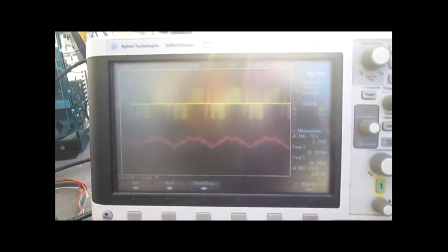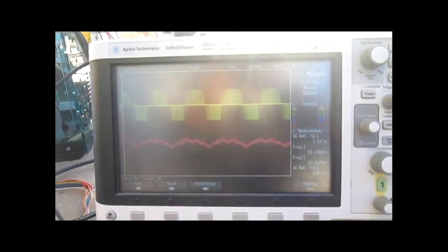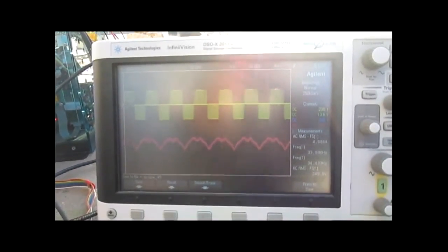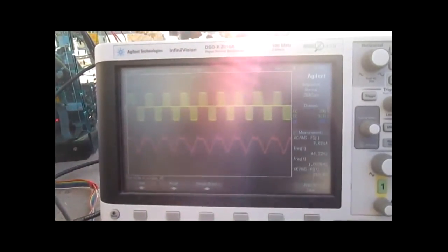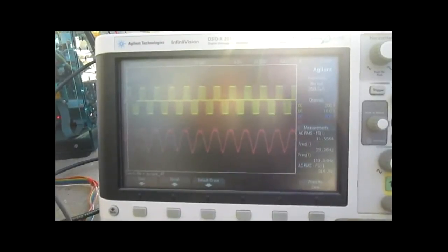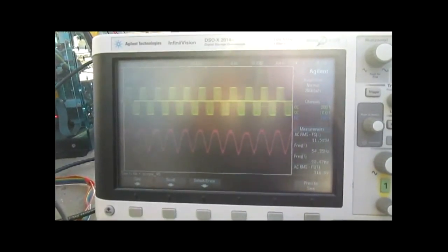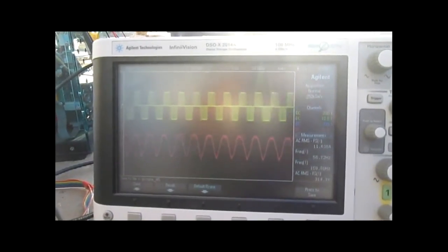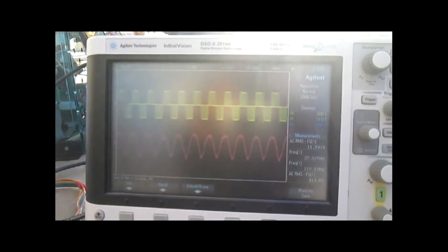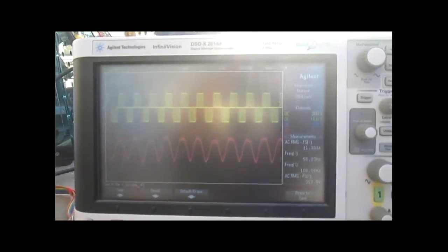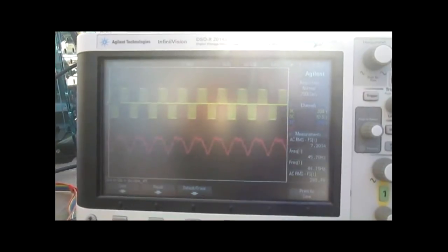Look at it, flow 100%, power is 3.5 kilowatt, valve is fully open. Flow is reduced, and it is simply consuming 210 watts. See, flow is reduced, valve is fully open. Look at the power, it is 290 watts. You can observe the power has reduced from 2.5 kilowatt to just 290 watts, which is a huge reduction in energy, which has a great application in the industry.